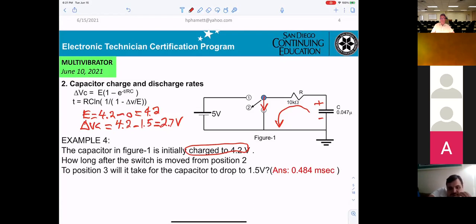Now you already know how the capacitor charges or discharges, so you can calculate more accurately. Normally they talk about the time constant. That means T equals R times C. That is the time for the capacitor to reach 63.2% of the maximum value. This is more detailed for doing the calculation.